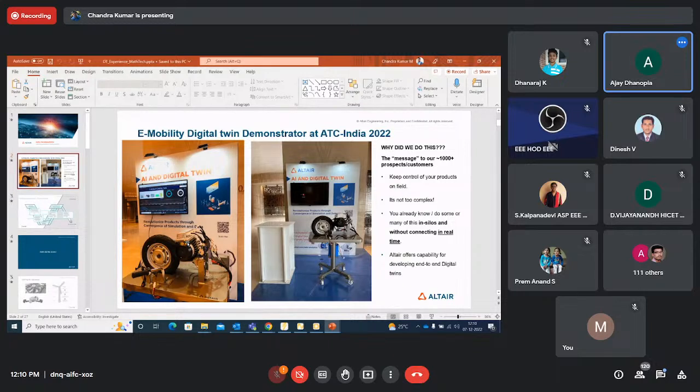Yes, that's why in this case, as a demonstrator model, we have taken only the state of charge of the battery as one problem statement. In your case, if you want to estimate other parameters, you can do n number of parameters for a digital twin. It's all about how we connect the dots. In this case, three simple steps. We do data acquisition from a physical device through the CAN protocol. After you collect the data, you apply that data on a mathematical model.